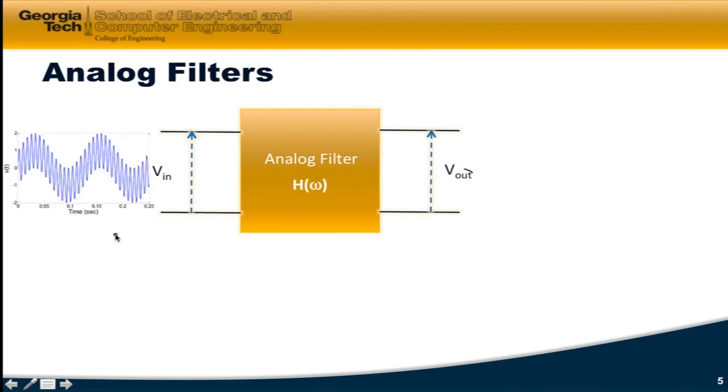So for example, suppose this is my input signal, and I've got two frequencies in there. A low frequency, where I can look at it here. It's kind of the average value of that. And that low frequency has an amplitude of 1. Then I have a high frequency superimposed on it with an amplitude also of 1. And if I write this out, I've got a cosine of 50t, that's the low frequency, and a cosine of 800t, that's the high frequency.